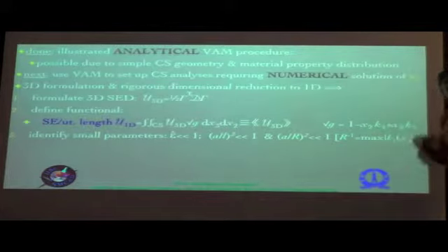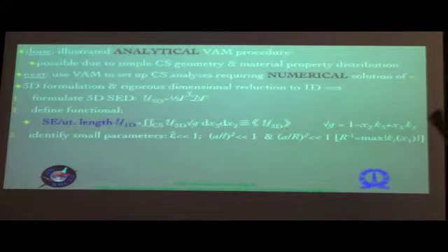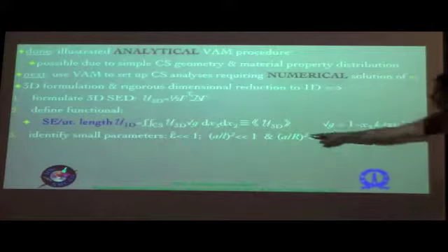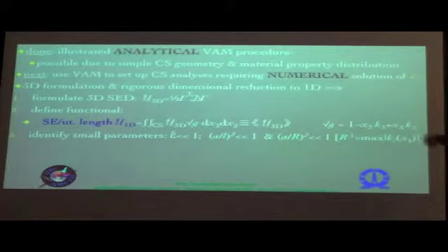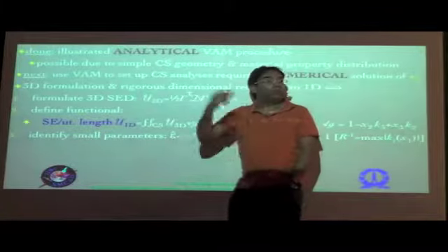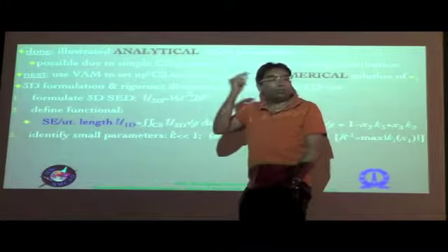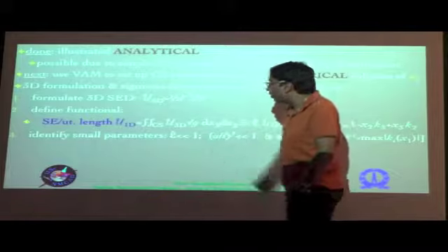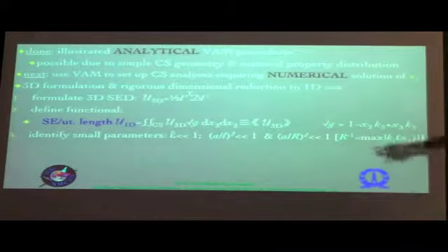Here instead we are dealing with a more general case where we don't have K3 alone, but we also have K1 and K2, and therefore when we're talking about the small parameters, we're talking about the maximum of those. Just as in the case of the strains, we talk about the maximum of all of these 6 measured numbers of the strain everywhere throughout the beam domain, right?